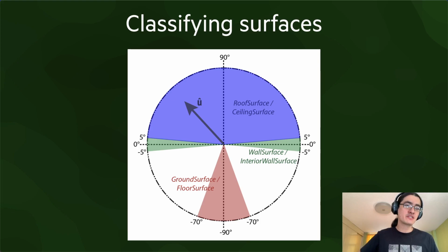And then from these interior geometries of each story, you can classify them to obtain what would be the walls, what would be the ceiling, what would be the floor, based on the angle. So most things that point downwards, even when they have a slope, because you have a tilted roof with eaves, are ceilings. Walls are pretty vertical, so there's a smaller tolerance, and floors are supposed to be pretty horizontal, maybe with some exceptions like for ramps and so on. So it's easy to classify surfaces based on the angle they have.